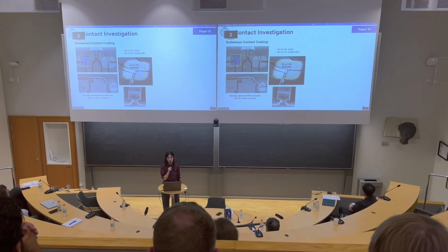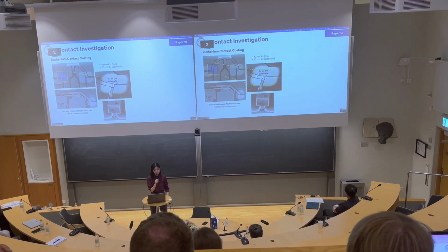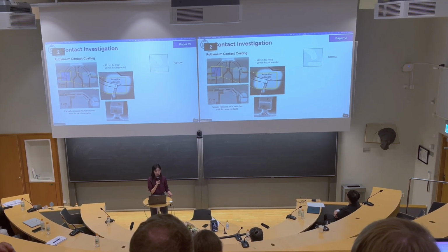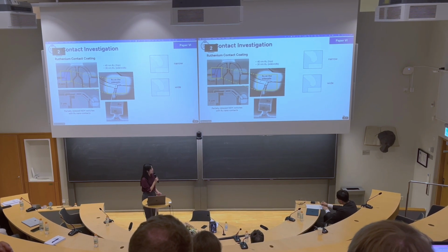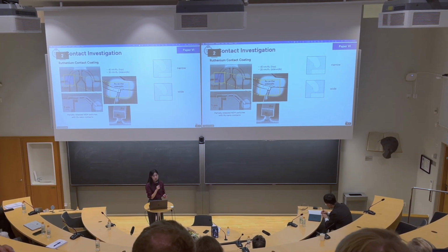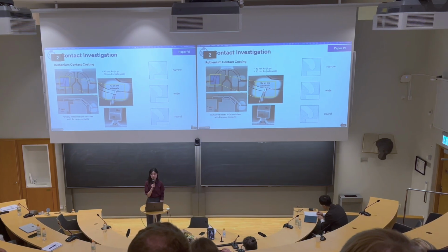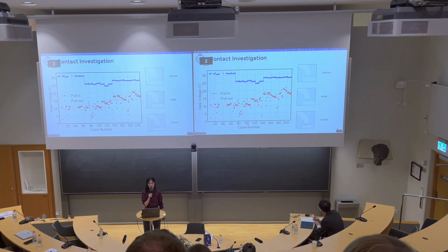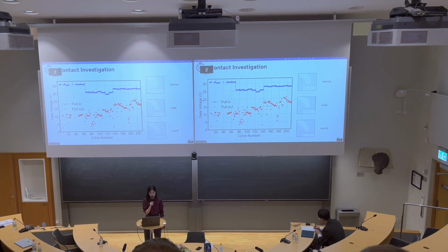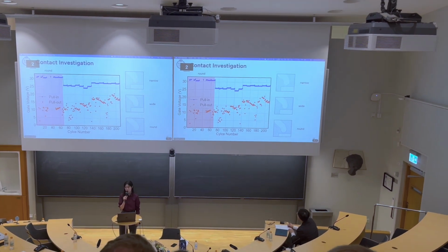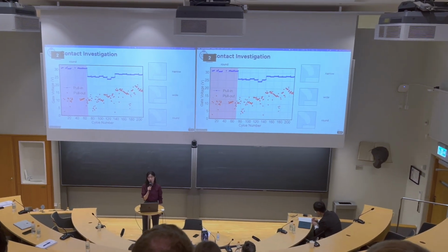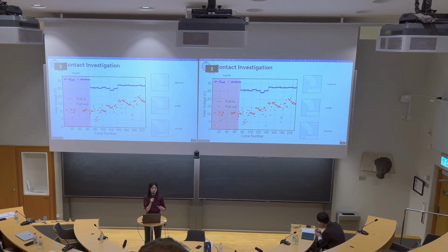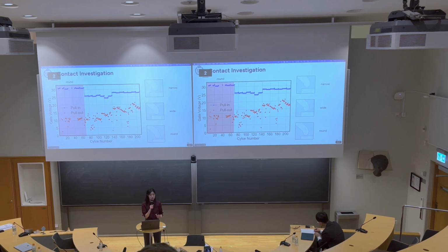And with this ruthenium contact, we further investigated 3 different types of switch contact shape. First is the narrow contact, then the wide flat contact, and then we also have a round contact. And those are the measurement results from the 3 different groups. So first, with the round contact, we see that they consistently have a larger pull-in voltage, which is over 30 volts, than the other 2 groups.